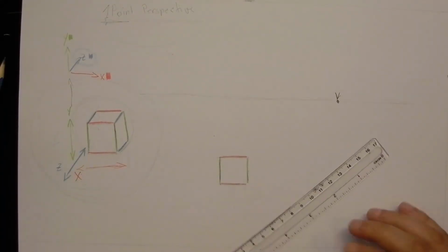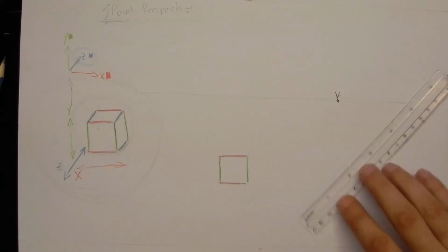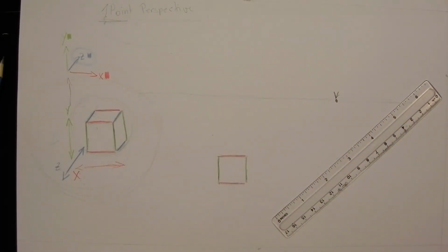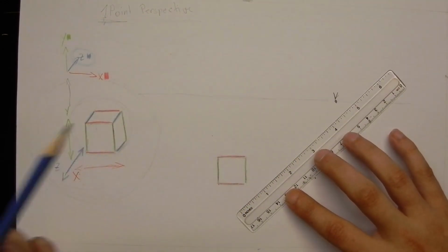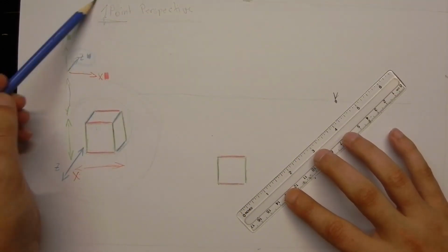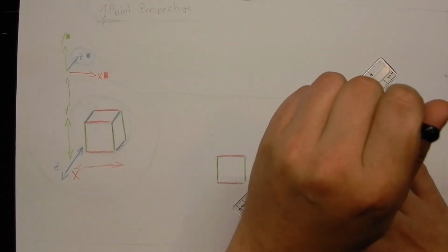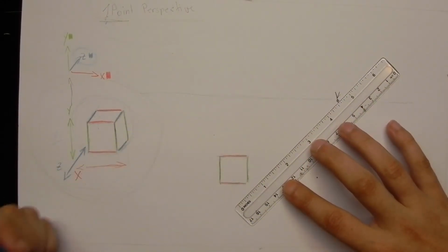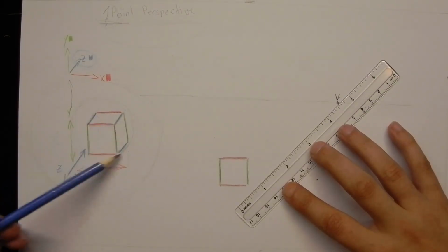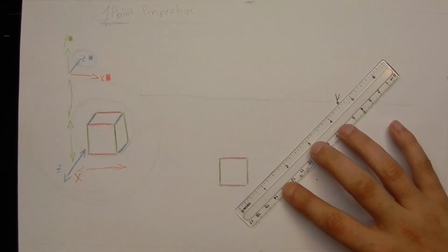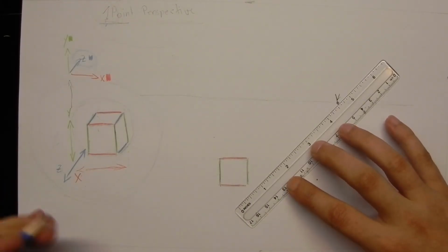We can do it freehand. We can also do it with a ruler. I just take a ruler here for achieving clearance on the paper. The vanishing point works as follows. Every line which is affected by the perspective, in our case with one point perspective just the Z lines, has to meet up at this vanishing point. And that's the reason why they are angled to each other. Those lines can't be parallel to each other. It just appears so in the sketch here, but we will see on the corrected cube it is not the case. And this makes our illusion of a 3D form.